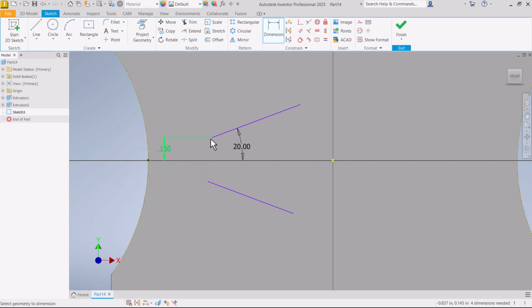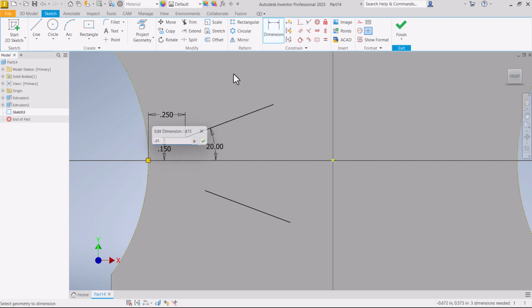Dimensions are constraints. There, now this endpoint of this line is stuck in place. This one is still free to move, but look at what can happen down here. This line is still free to extend in either direction. It is the position of the line that I constrain with a symmetric constraint. If I don't pick the endpoints directly, then they are not going to be part of that symmetric set.